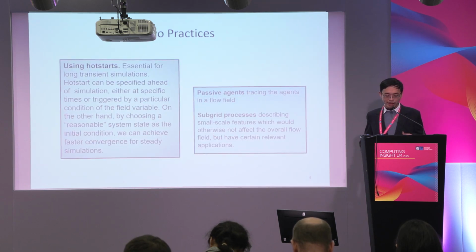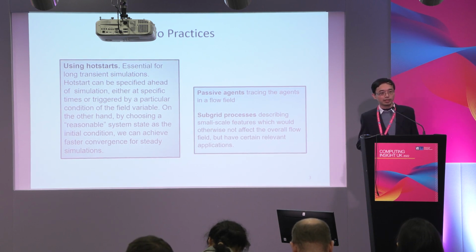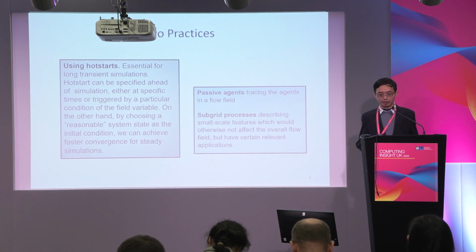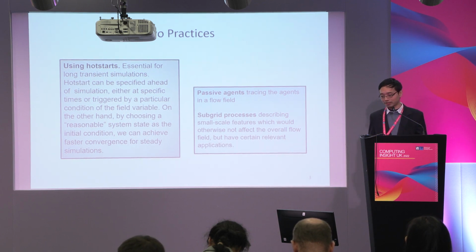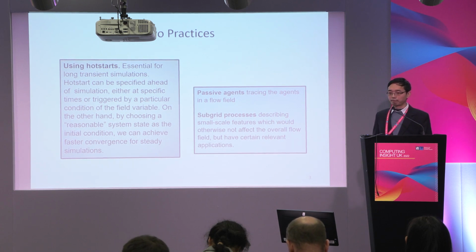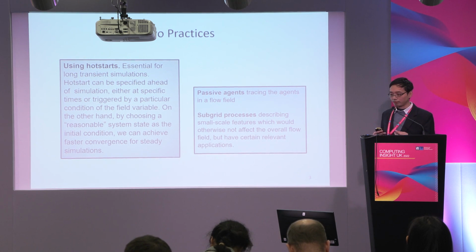To handle such very long and complex simulations, there are certain tricks to speed things up. Aside from the obvious techniques such as parallelization, I have found a relatively less considered one: using the hot start and reusing previous runs for computing new scenarios.